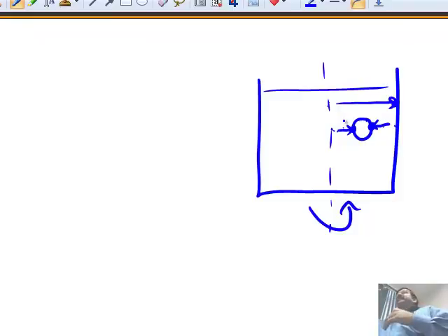In the gravitational field, it's linear, rho g z. In the centrifugal field, it is rho omega squared r squared. It goes actually as r squared radially. So this pressure acting on the outer surface is larger than the inner pressure. Do you understand? That's clear, right? So if you do the integration around that using the pressure profile, you'll find that there are more forces pushing it towards the center than the force that is pushing it out.